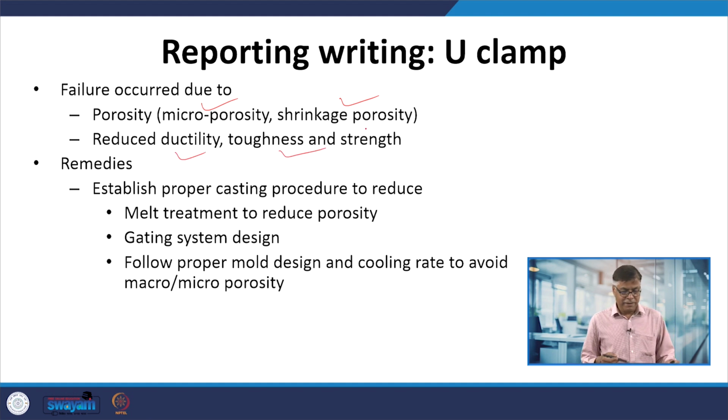As a remedy, it was suggested to do proper melt treatment and reduce porosity, and design the gating system properly, so that proper thermal gradient is maintained during solidification, and follow proper mold design and cooling rate to avoid micro and shrinkage porosity. That is all.